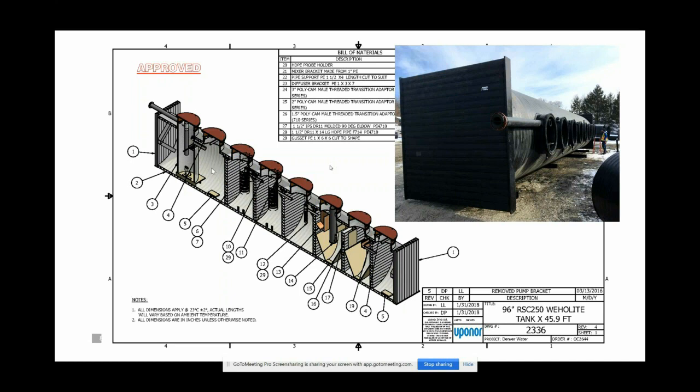The tank is within an equalization volume tank, and then you have a 3-stage MBBR tank. The vertical screens inside these chambers are actually media retention screens. Following that, you have a 2-stage clarifier. And then the final tank is effluent pumping.